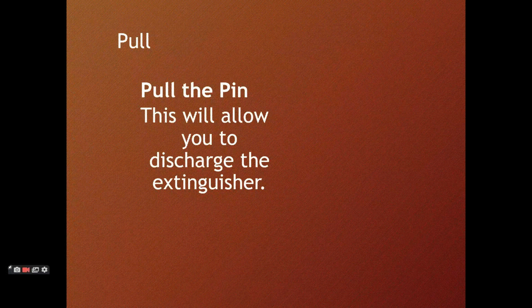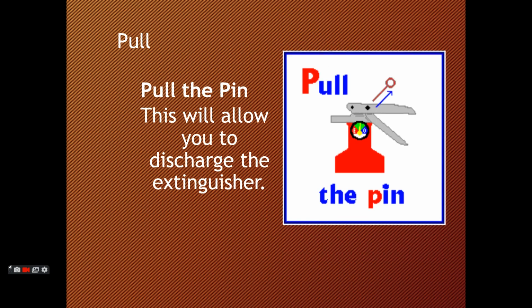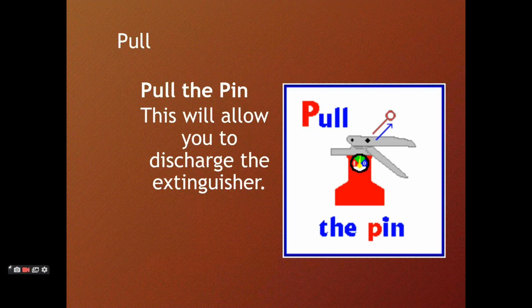So pull means what? Pull means pull the pin. This will allow you to discharge the extinguishers. Whenever you are pulling, what do you have to pull? You have to pull the pin. There will be one pin inside this hole. You have to pull the pin before you start to use an extinguisher. If the pin is there, you cannot squeeze these two handles. Once you remove the pin, only then you will be able to squeeze.